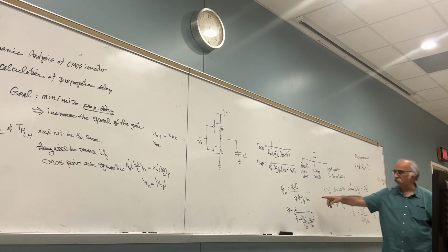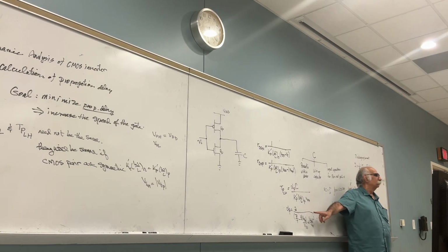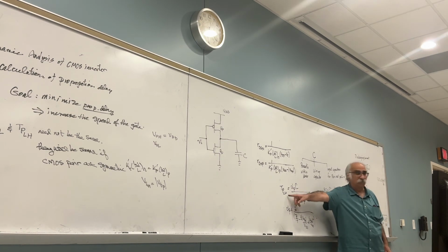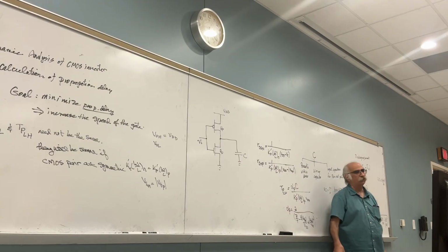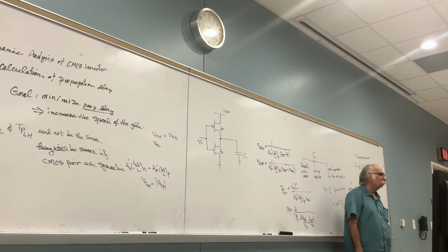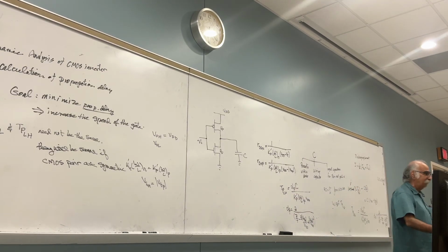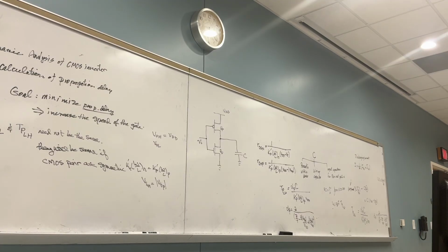I want VDD here. What do I want VDD to be? I want it to be high, so that this one becomes low. And one more time, why do I want this one to be low? I want my devices to be faster. So I will need to make VDD high. But if you make VDD high, the power dissipation will become much higher. Agreed?